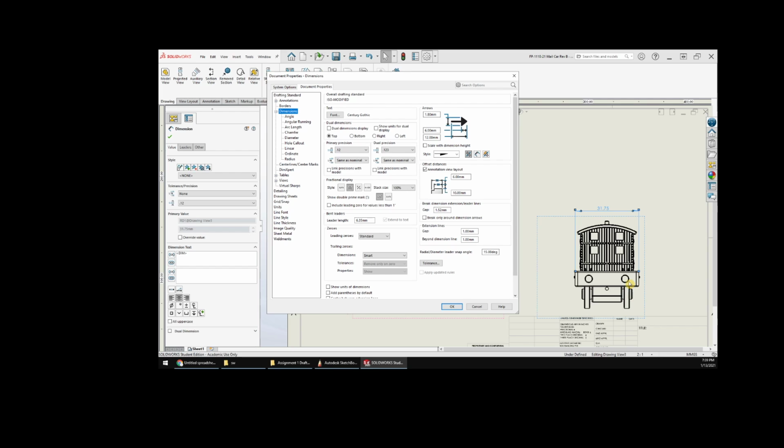Chevis, yeah. I'm following along as you're going, and I'm jumping back and forth. Could you repeat how to change whether it's rounded to 1 decimal place or 2 or 3? Yeah, so where that comes down is over here in the middle, primary precision. Okay. And you just adjust that. I'm on this right now, so okay, I see it. Thanks.